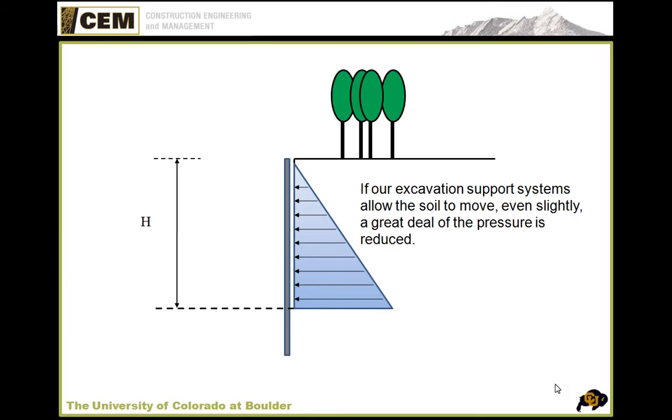Now, when we have a sheet pile wall, and this is not a reinforced concrete wall, not something that's going to be rigid and unyielding, but a sheet pile wall, we will allow that wall to move very slightly. At the top of the excavation, we're talking about just a fraction of an inch or just a little over an inch.